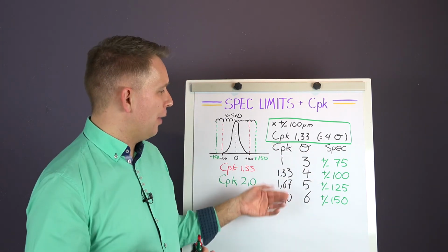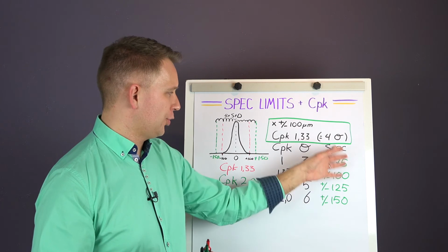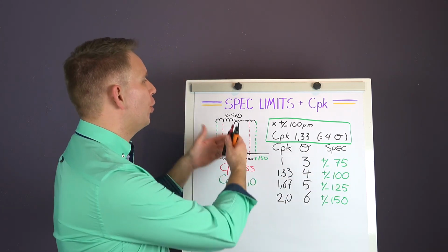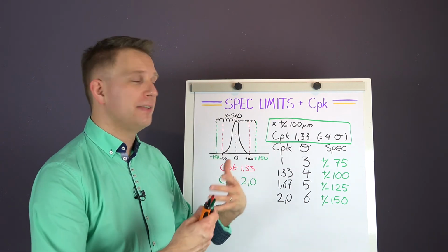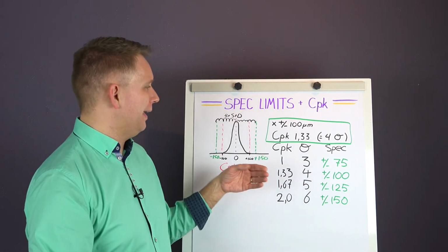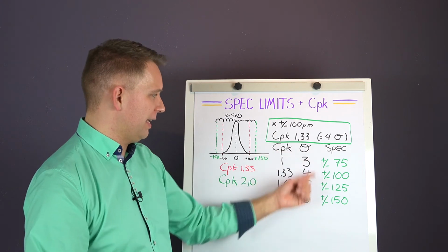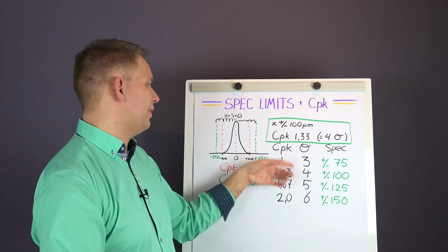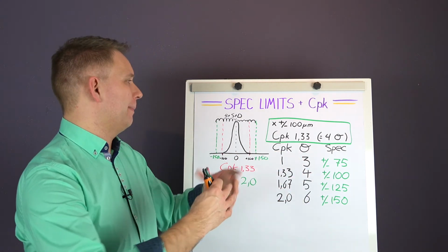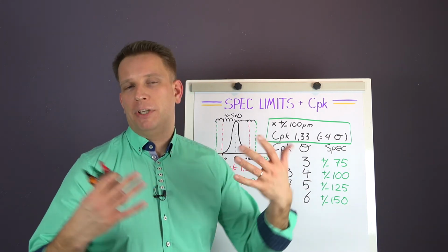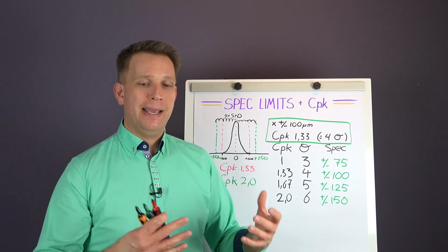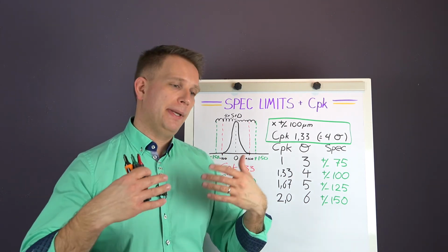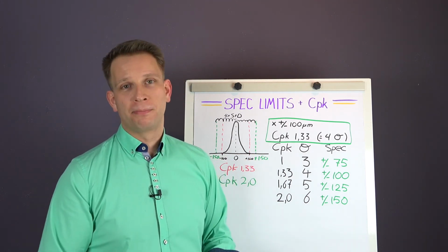So how can I compare tolerance limits to the known standard deviation, because we know here from this example process that the standard deviation is 25, and how do you translate it into standard deviation or sigma level, and how do you translate that into CPK, and how can we make this a language to speak between supplier and customer, and maybe technology quality departments.